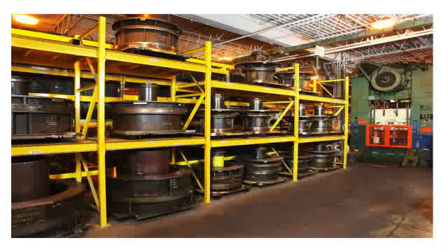Most of the time, the decking on the shelves is either a heavy-duty steel solid shelf, or sometimes they just run a riser bar front to rear and basically set the dies on those. Your loads on these kind of racks can get pretty high at times. 10,000, 15,000, 20,000 pounds of shelf load are not unusual.